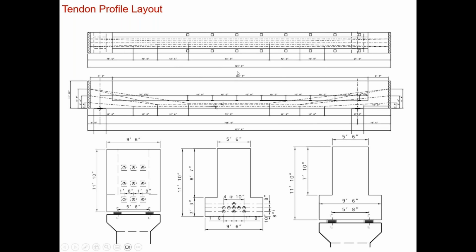A quick way to estimate the tendons is basically estimating the ultimate moment on this bend from all dead loads, factored dead loads, and live loads. And simply you can just take this moment and divide it by a lever arm from the centroid of the tendons to the location of the compression force here. At ultimate, you can even estimate this lever arm like 80% of the D from the section, from the centroid all the way to the top, and come up with the ultimate tension force and divide it by some fps value, an estimated value for the stress in the tendons at the ultimate stage,